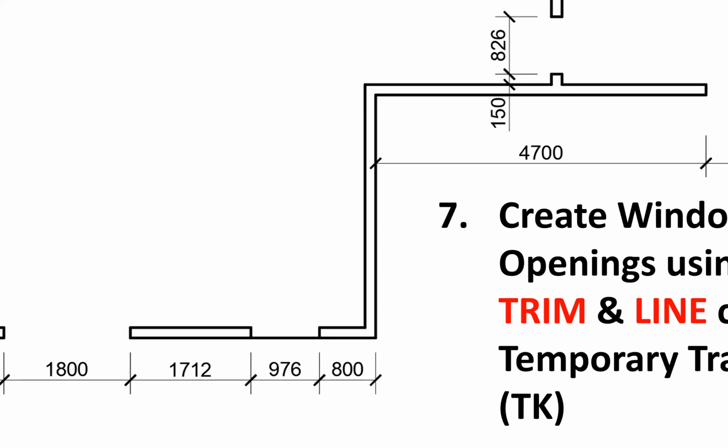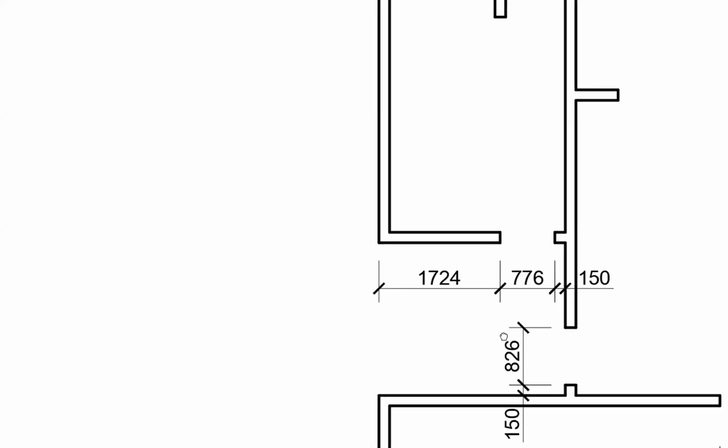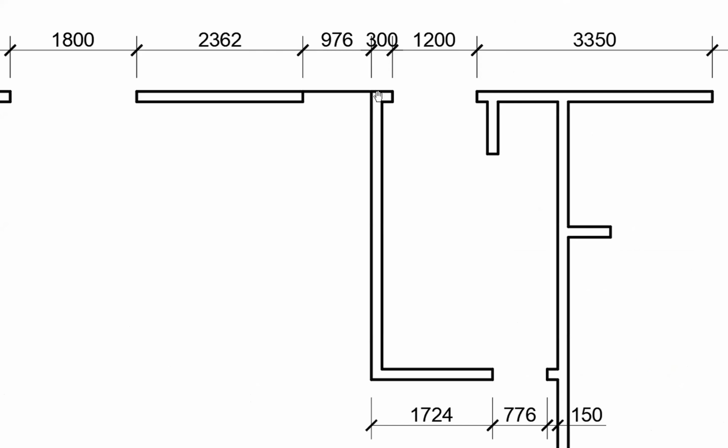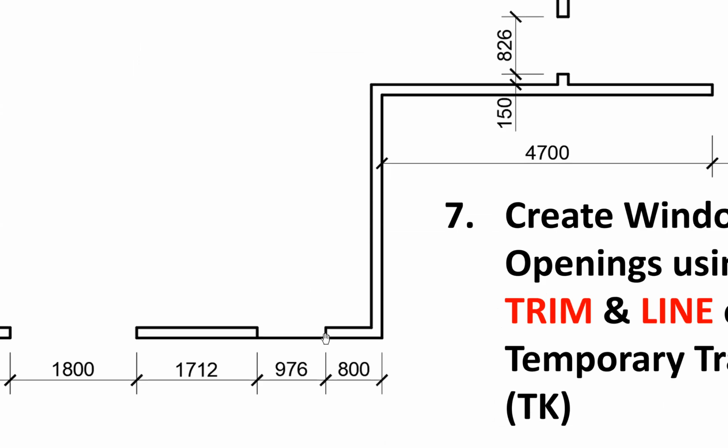The window jamb is also the surface. So we have window jamb and we have door jamb. We have door frame going against door jamb and window frame going against window jamb. So we are going to draw door jamb on one side for the bathroom, door jamb on one side for the back door, and then we will just offset the other door jamb with the offset command, right? So we're only going to start with one side.